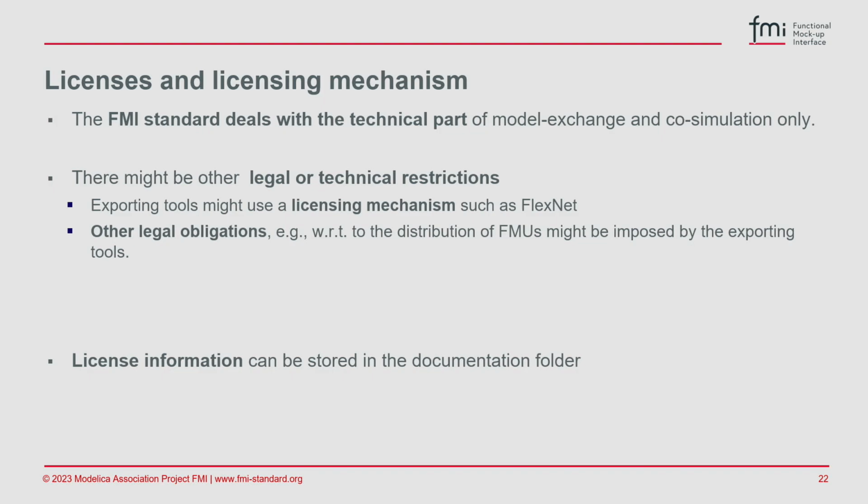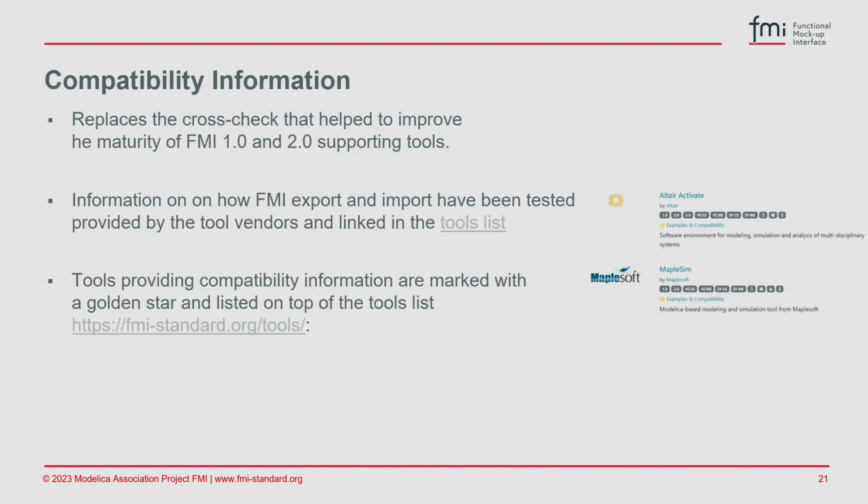Quick question on the previous slide. You mentioned the compatibility issue. Could it be that there are 2 FMUs that are not compatible with each other in the correct FMI environment? If everything is done right, then it shouldn't happen. But it's programmed by humans typically, and they make mistakes. We have seen lots of corrupt FMUs, and there are ways to validate them.